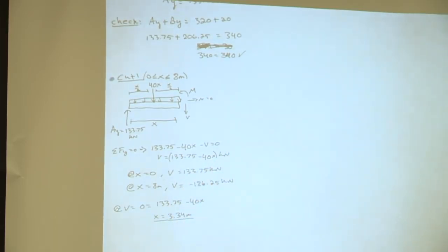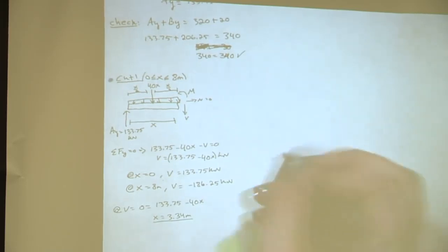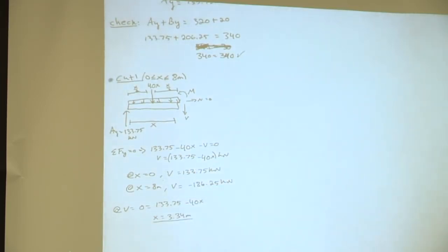Okay, now what do we need to do? Start graphing? Well, we can continue the cuts and then we'll graph it all. Do we have any other equations we need to solve for this cut? The moment equation, yes. And how do we solve for the moment equation? We could integrate the shear. Okay, awesome. So we could integrate the shear equation. What else could we do?